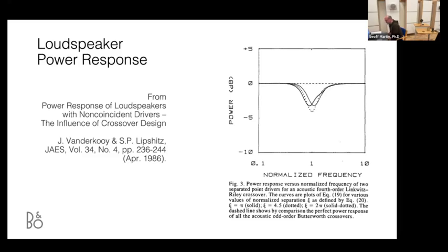Of course, if your drivers aren't omnidirectional, if you do have some kind of directivity associated with frequency with those drivers, then that power response curve won't be flat. It'll be tilted downwards into the high frequency. So the higher up you go, the more it slants downwards. But the dip in that response will still be there. So this was an issue that one of our acoustic engineers had thought about for a long time, and he decided he was going to come up with a solution.